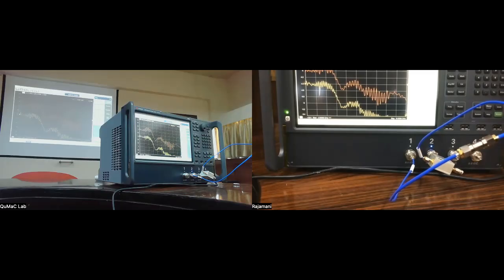So what he's referring to is an interference pattern, is that usually when you have any cable in the system, there will be some reflection at the two ends. And that means that that can set up a standing wave, a weak standing wave. So there will be frequencies where you'll get constructive interference and slightly destructive interference. And that will give rise to small changes in reflected power or transmitted power, depending on the exact situation. So if you change the length of that cable, then the two reflection points change. So then the period over which you will get the constructive and destructive interference will change.